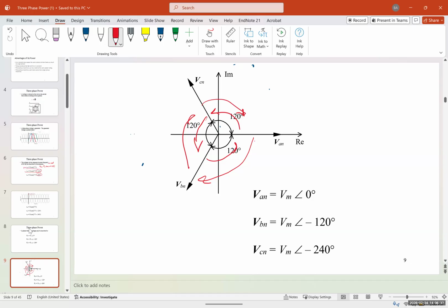This is the principle of how an elevator motor works. Goes up and down if you're opening or closing a garage. This is how it works in a three-phase motor. DC is completely different. So what we do, we want to change the sequence of the phase, and we do that by simply switching two phases together.